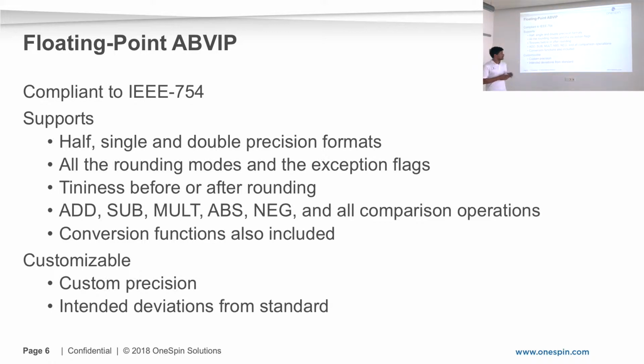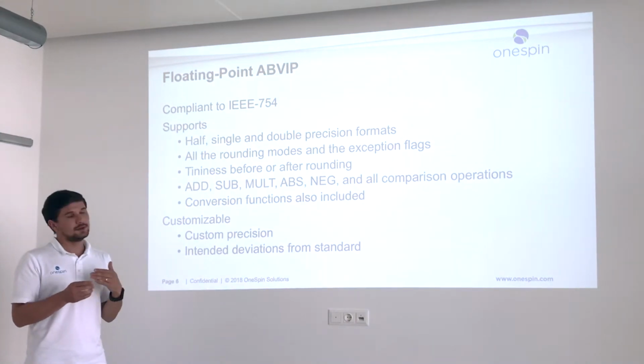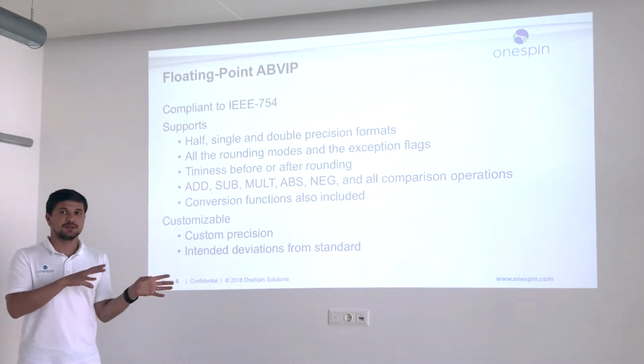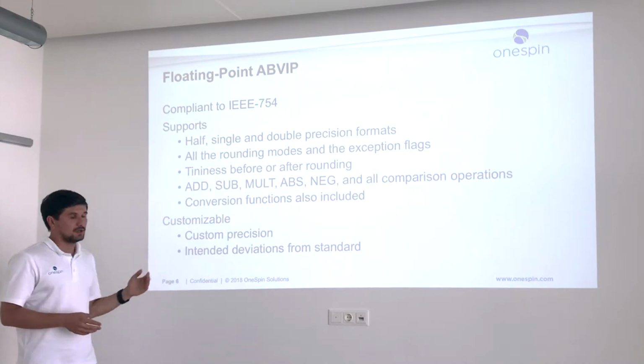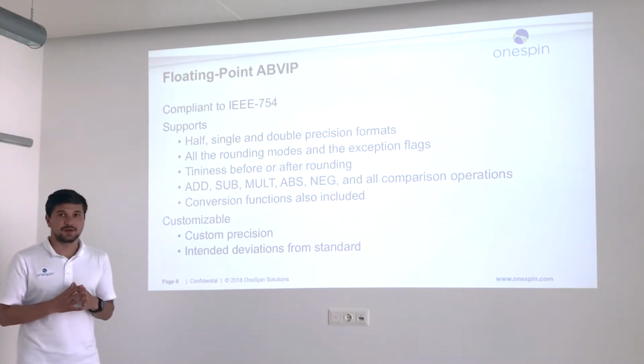Conversion functions are also included, from double to single precision and from single to half, and it is highly customizable. If the user's floating point implementation required some deviations from the standard, this is also easily customizable inside the verification IP.